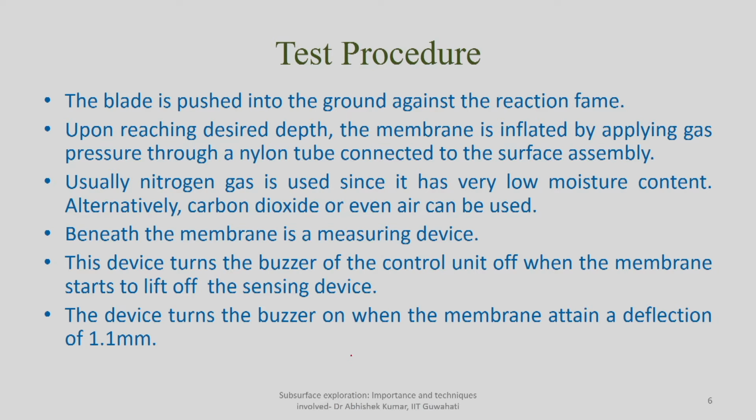So this blade is pushed into the ground against the reaction frame. In order to push the blade into the ground, you have to have some kind of external or reaction frame, with reference to which this blade is actually getting pushed into the ground. As you go to deeper and deeper layers, there will be a lot of confining pressure. So the reaction applied by the reaction frame should be much higher than the confining pressure, otherwise your blade will not be able to penetrate at deeper depth.